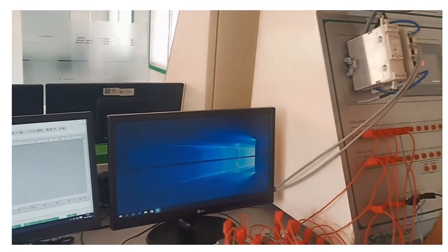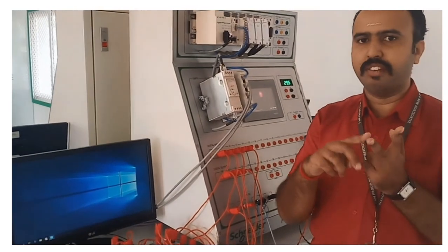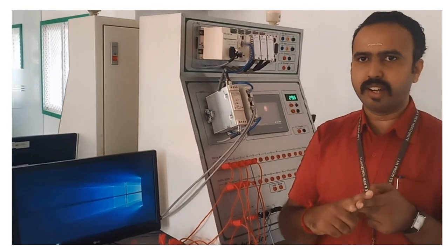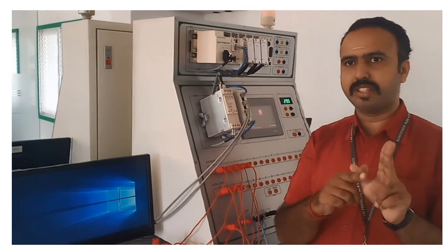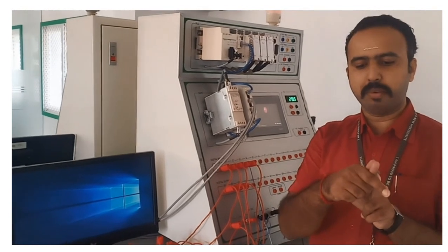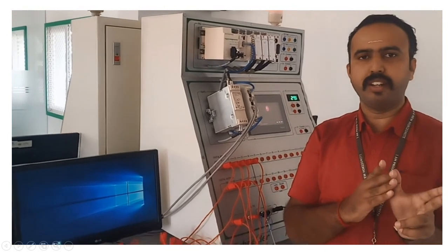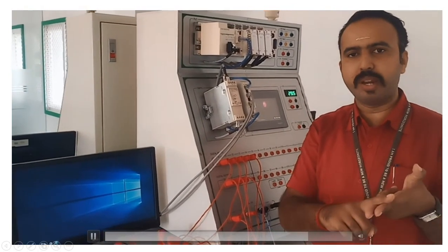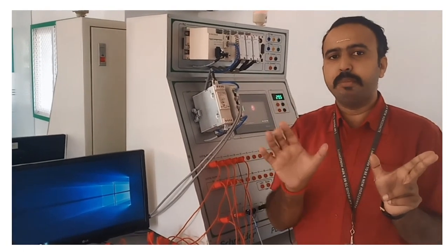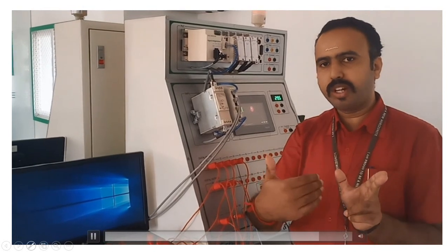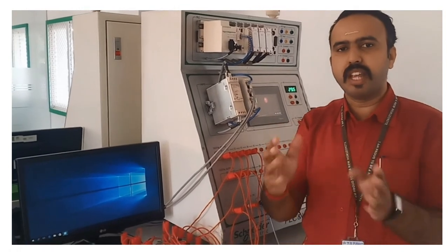But as per our application, we are drilling the workpiece the first time. If it is not satisfied, we are going for the second time, and we are continuing the same process twice. So here we are using a timer as well as the counter. For drilling twice, we are using the timer, and for counting the cycles, totally 4 times the drilling is happening in it, to ensure that we are making 2 timers and 1 operate block and 1 compare block. The 5th application can be modified by replacing this operate block and compare block, and by using a single counter we can modify it, but same operation.